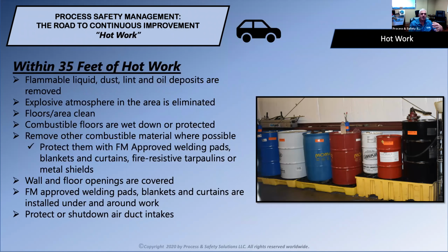So in general, within 35 feet of hot work, you must ensure that flammable liquids, dust, lint, and oil deposits are removed, and explosive atmospheres in the area are eliminated.